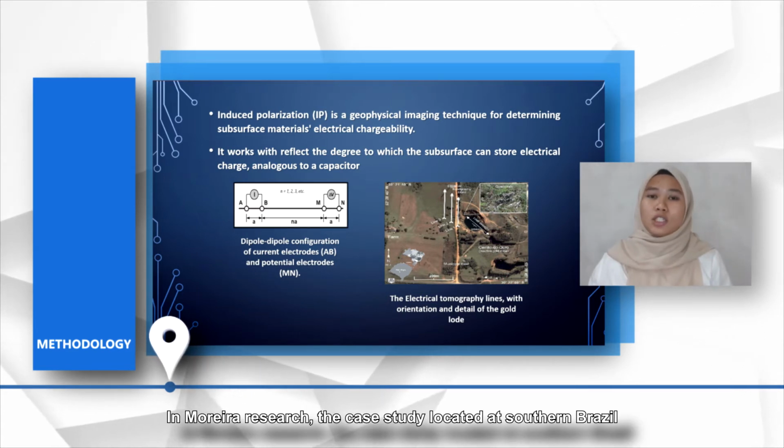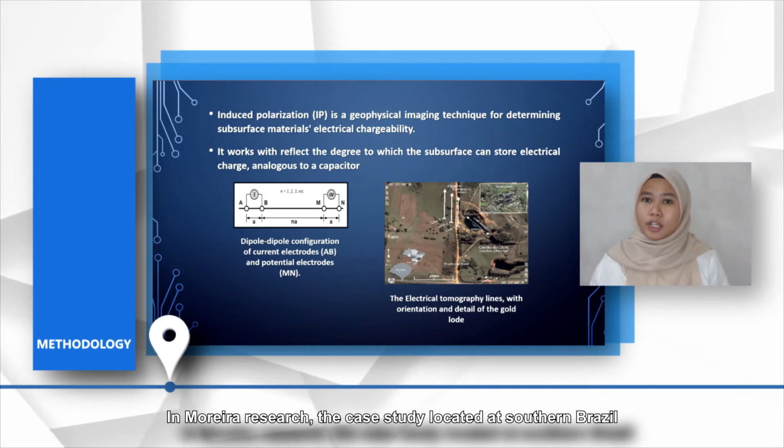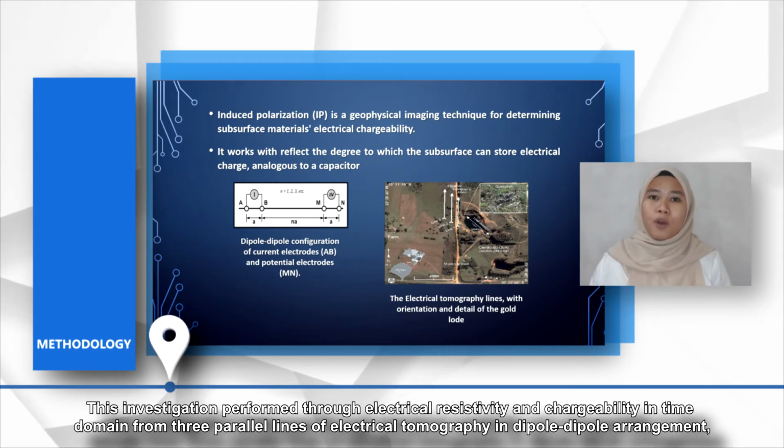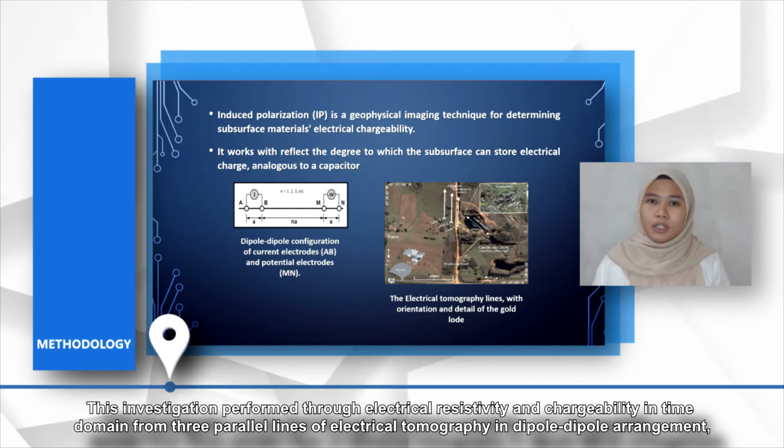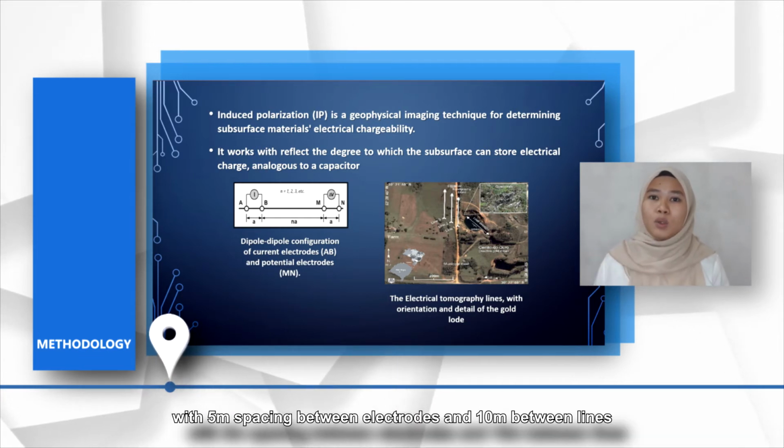In Moreira's research, the case study was located in South Brazil. The investigation was performed through the electrical resistivity and the chargeability, same as before. In time domain, there were 3 parallel lines of electrical tomography in dipole-dipole arrangement, with 5 meters spacing between the electrodes and 10 meters between lines.